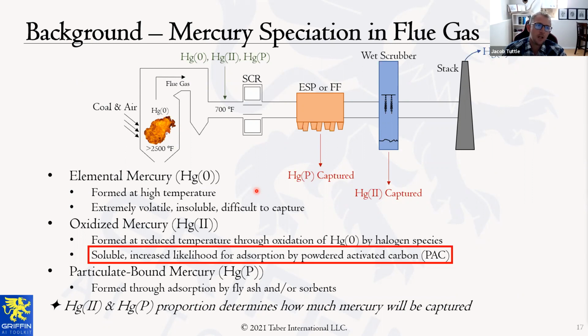What's problematic with this is basically we're throwing a whole bunch of black dust into the process, which ultimately affects other emissions and affects the process in a number of other ways as well. Particularly in this application, the opacity readings at the stack of this plant, very clear relationship between higher PAC injection rates and opacity rising.